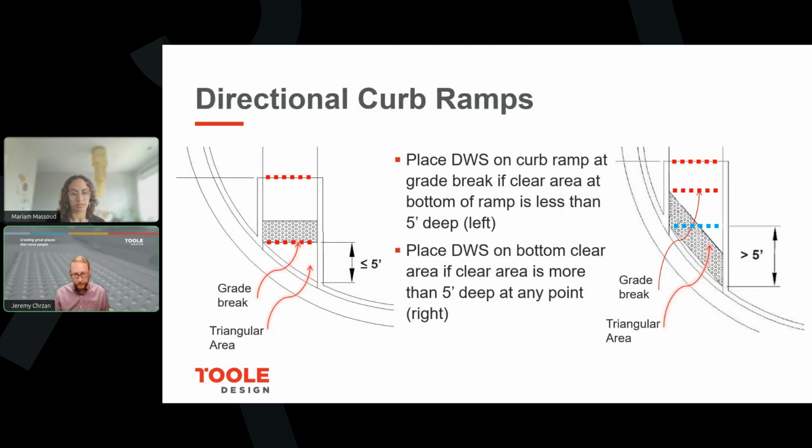So when it comes to directional curb ramps, if we have identified that the orientation of our crosswalk in relation to a standard style perpendicular ramp is exceeding that 20 degrees, then we seek to align the orientation of the directional ramp with the orientation of the crosswalk. And when we do that, we measure the distance from our curb line to where the detectable warning surface would be located on a standard design for a curb ramp. That's what we're seeing on the left here.